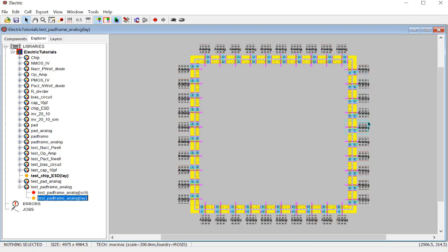Okay. So for example, I have 6 pins for the op-amp. I want to use 1, 2, 3, 4, 5, 6. I want to use these 6 pins starting from here. And I need to export this guy and this guy, because this guy is being connected to the internal circuits, and this guy is being used for the total outputs. So when they're fabricating the chips, they need to know what are these final outputs of your chip, right?